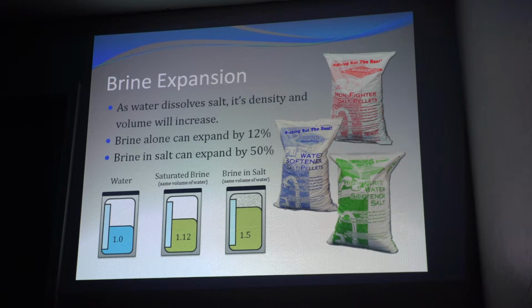Because if you compress it when it's too warm, you get too soft of a pellet, and you get mushing in the brine tanks. If you compress it when it's too cold, it falls apart. It dissolves, but it just falls apart in the bag. So, who would have thought that there's a lot of science to salt?